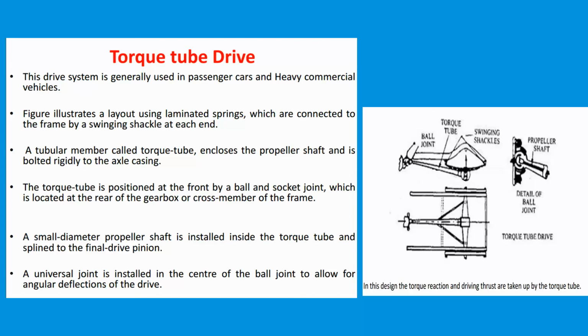The purpose of the torque tube is to hold the rear end in place during acceleration and braking. Otherwise, the axle housing would suffer axle wrap, such that the front of the differential would lift up excessively during acceleration and sink down during braking.